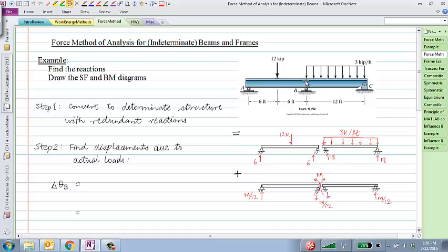A better method actually is to imagine this beam as basically two simply supported beams. Okay, so I'll make a cut here to make those two segments A to B and B to C independent. Now they are two simply supported beams, and I have introduced only one redundant moment in this case, right? So instead of a redundant force, I'm introducing a redundant internal moment. And the benefit of that, of course, is that now the left-hand side structure becomes symmetric, the right-hand side structure becomes symmetric. All I need to do is find what that internal bending moment M would be to make sure that the rotations under this load and this load get cancelled off by the rotation due to these redundant moments.